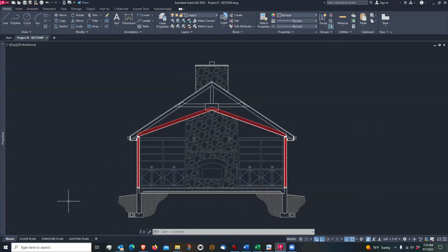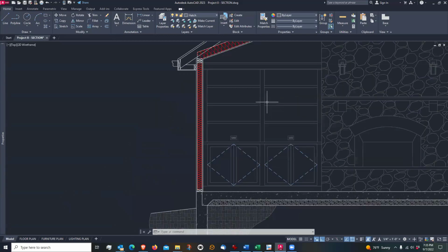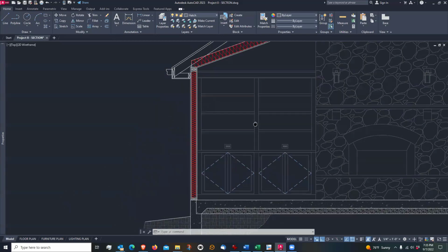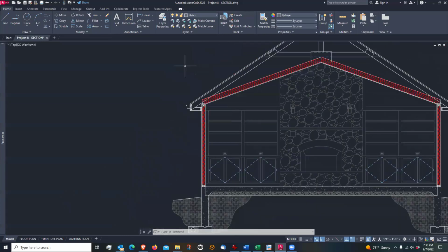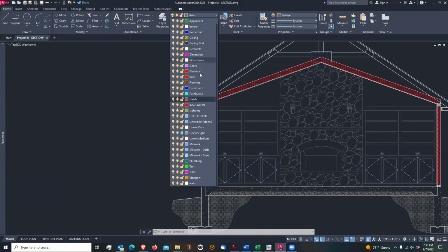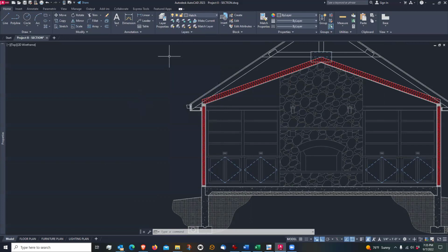You know what? While I'm at it here, I know that I have this line weight layer locked. I'm going to unlock that layer. So a couple ways I can do it. I can go down to the drop down here, and there it is. It's locked. I can just click unlock right there, and that would work. Or again, these little buttons right here, this unlock right here.